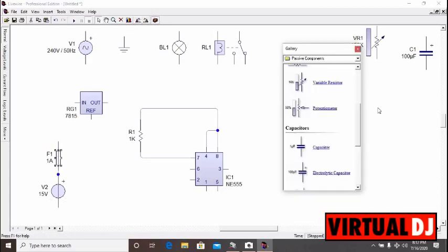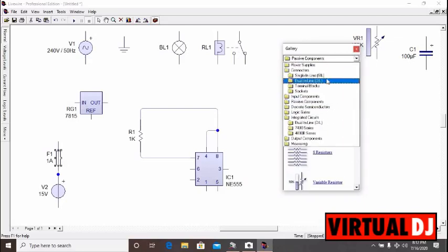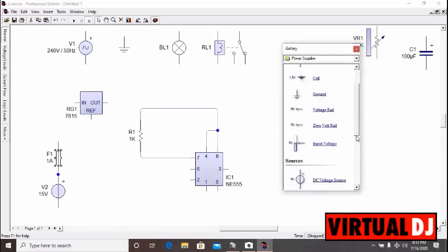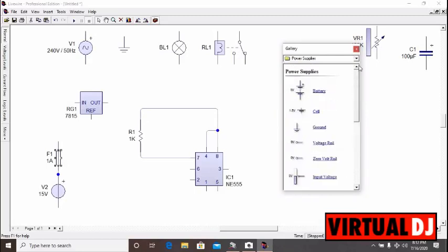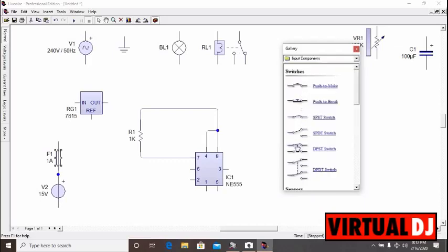Then my switch. So you could decide not to fuse your circuit. I guess most adapters come with their own fuse in them, so it's just making a double insurance for your circuit. So I'll be using a single contact switch here. So let me change the direction. Good. So this is it. So I'll be connecting pin 1 of my voltage regulator to the switch.